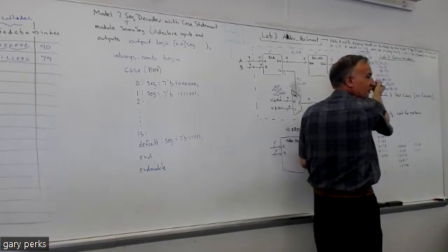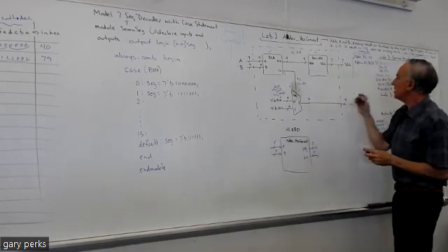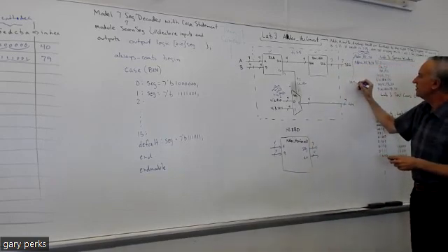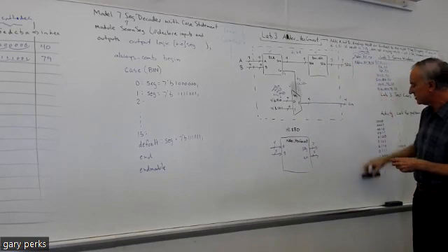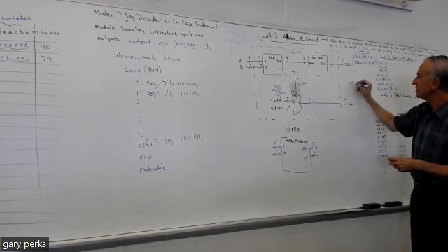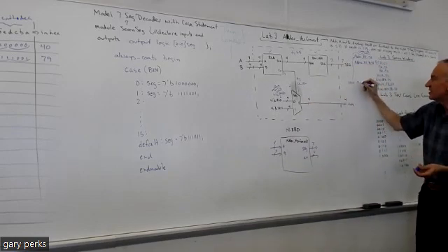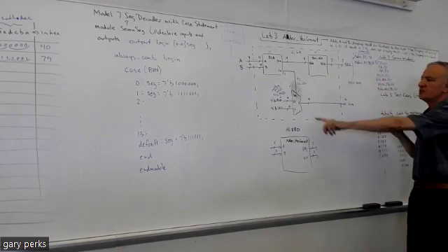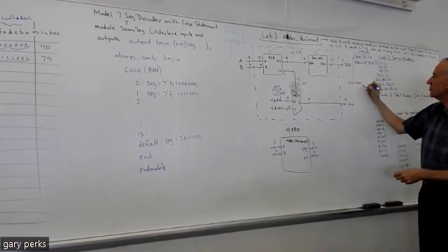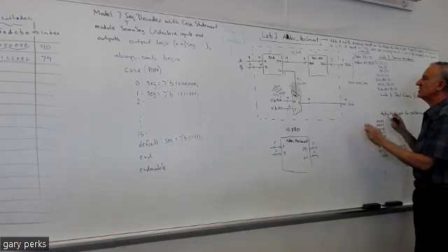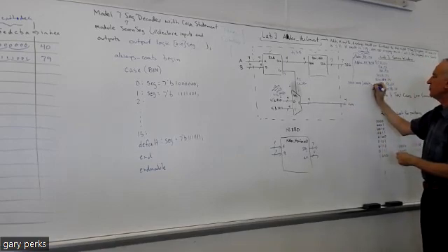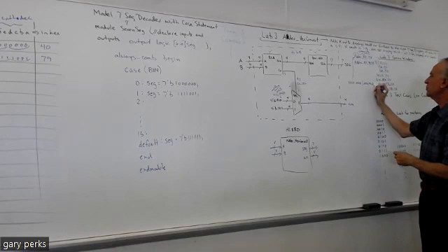So in the line for the mux, you would have mux, because remember how we talked about last week, the first thing is the file name. If you want to make the connections for this mux, you start with the file name, then there's a label, maybe you just call it mux 0 since there's only one mux. And then you start making the connection. So to make this connection, it's parentheses, you would just go .0. Now, like I said, I don't think you can use numbers, so spell it out instead of just putting a number. But you put .0, and then in parentheses, you put 4 tick mark B 1, 1, 1, 0.